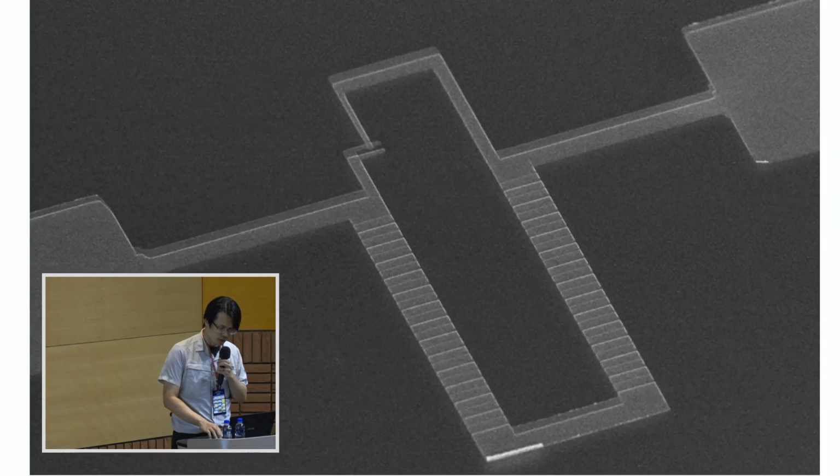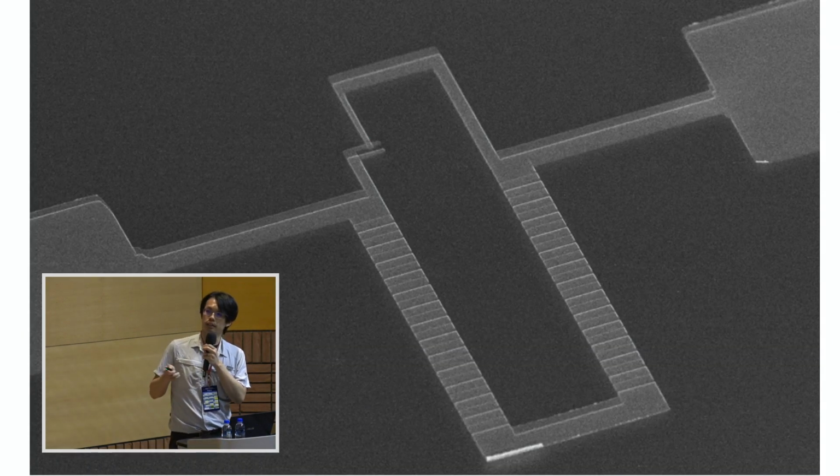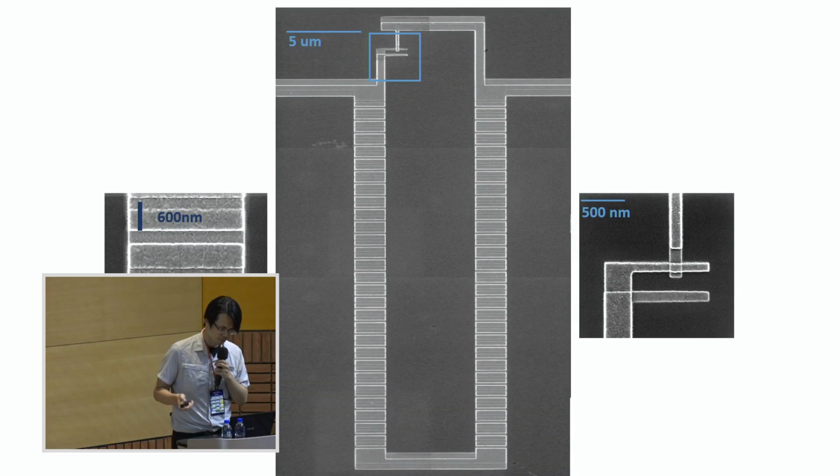So later at Maryland, we made these fluxonium in a 3D cavity, so that we can specifically tune up the fabrication conditions for the fluxonium qubit and make it simpler with this 3D cavity. This is an SEM image of an enlarged fluxonium qubit on top of a silicon substrate. Okay, and you can see that these are the Josephson junction array.